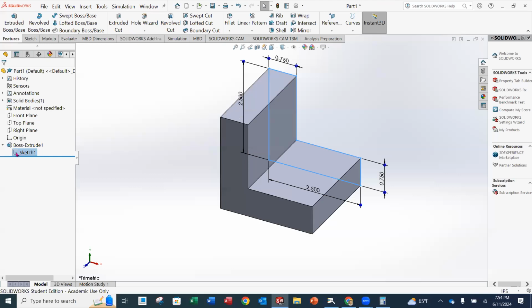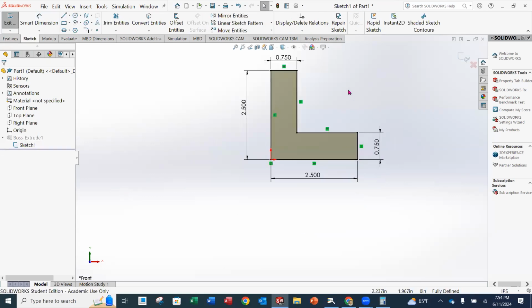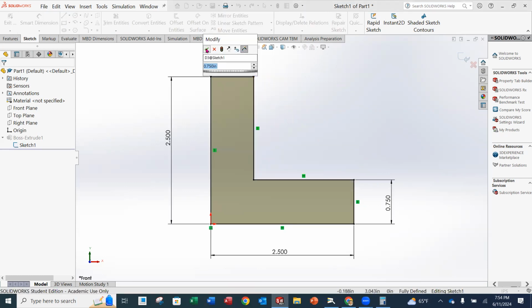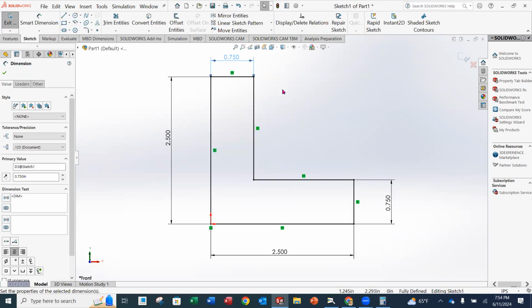The other place that I can do it, I can go back into the sketch. So if I go over to the sketch here and I left click on it, you're going to notice that we get a series of boxes here. The upper left-hand corner one is called Edit Sketch. You can also go there to do the very same thing, and it goes back to that sketch that you did earlier. And again, you can double click on anything and you can edit that value.